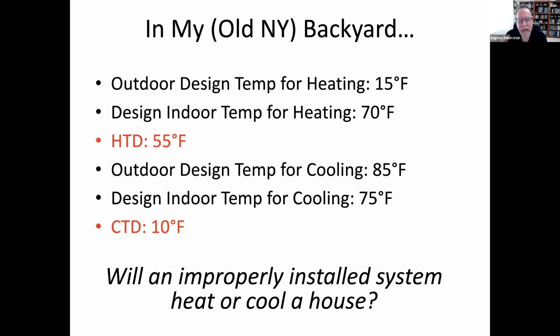So with a design indoor temperature for cooling of 75, we're looking at a 10-degree delta T from inside to outside. So our heat pump system, when it's operating in cooling, and I'm talking about traditional single-speed heat pumps, when that heat pump system is operating in the cooling mode, we're really only moving heat against a 10-degree temperature difference.